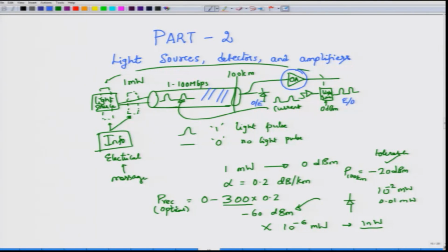And of course, we do not really have to do that, because luckily around the mid 1980s people discovered or invented the optical amplifier, so that you would never have to convert the optical signals back into the electrical domain and again convert from the electrical domain to optical signals. And this optical amplifier, the prominent one which was studied first and then brought into the market, is called the erbium doped fiber amplifier. Okay.